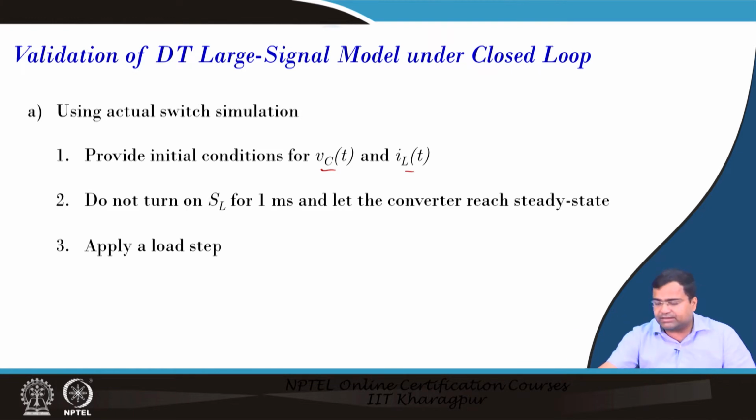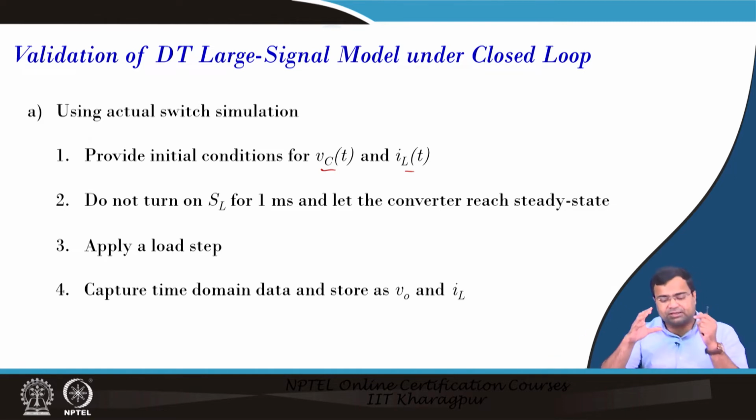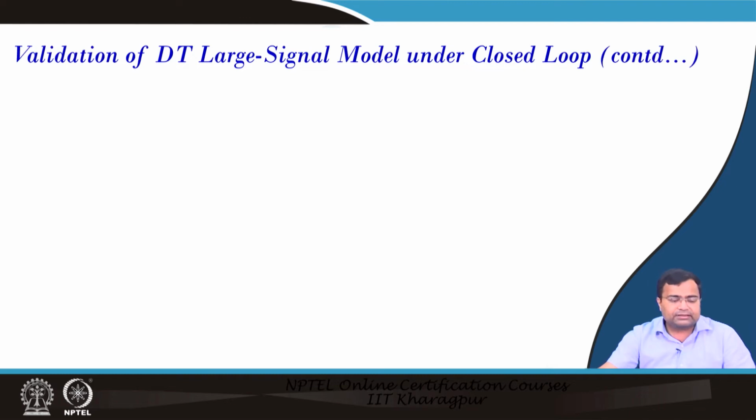Then we will apply a load step. I have told you that it will change to another load resistance. Then we want to capture the time domain data and store it, and I will show you all the steps. Once you store the switch simulation data, which includes initially one load resistance, then after some time another load resistance with the transient as well as the two steady state conditions, we will store this data in the workspace.